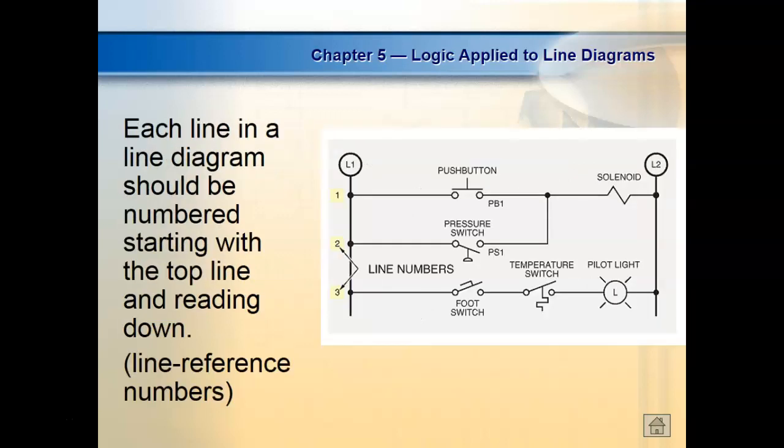what we do in motor controls is we don't number rungs, we number lines. So every wire that runs horizontal, not vertical, that runs horizontal, gets a line number. Basically any wires that are connected together are one line. So this would be a line, this would be a line. This doesn't get a line because it's in the same what? Path, right? You understand that?